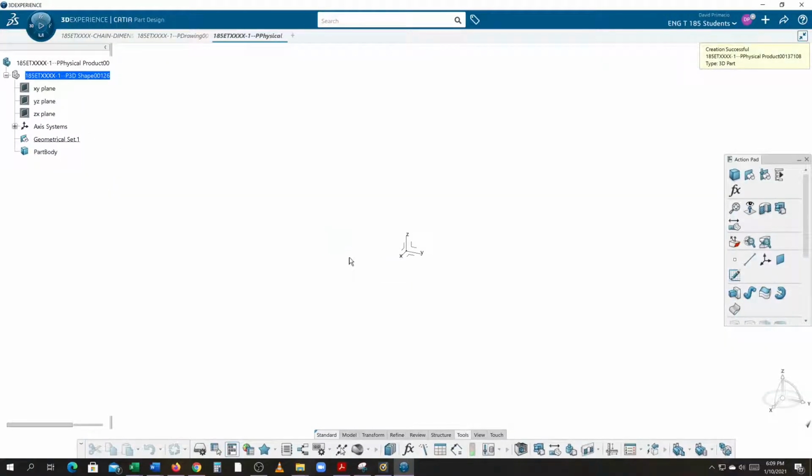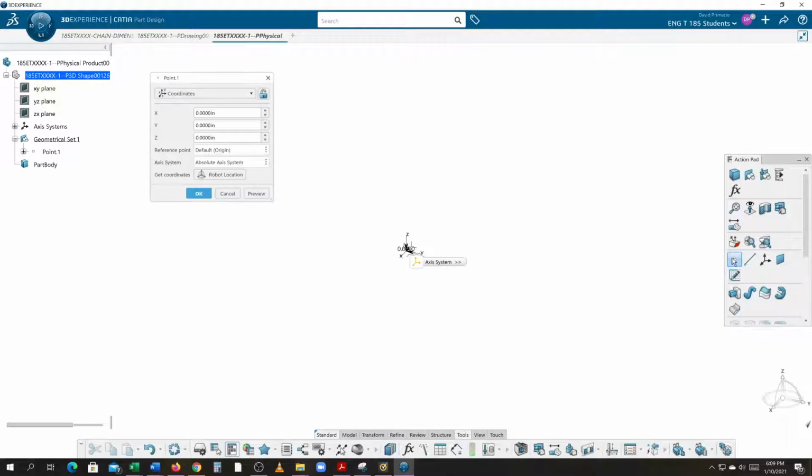And we're going to build a part similar to the last one by creating a local axis system. Again, I'll create that same point. We'll go to points, and we'll do it at station, our X at 0, Y at 2, and Z at 2. You can see it's giving me coordinates from the axis to let me know where it's going to locate that.